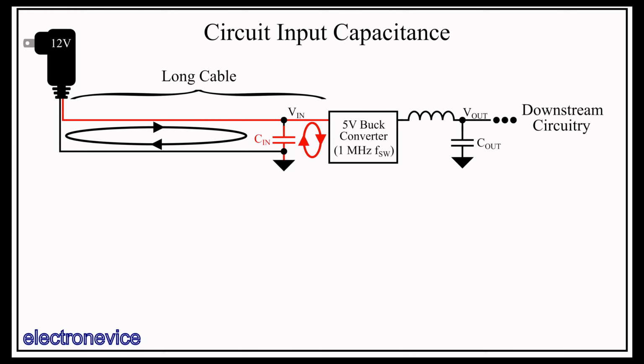Input capacitance is not just used on power converters, it can also be used on anything that draws current at medium to high frequencies. In practice, we put some decoupling capacitance on nearly everything with a voltage rail. Similarly, there is a large amount of capacitance put on the output of this switching converter, along with a series inductor to filter out the pulsed output current. This capacitance is called output capacitance, or sometimes filter capacitance.